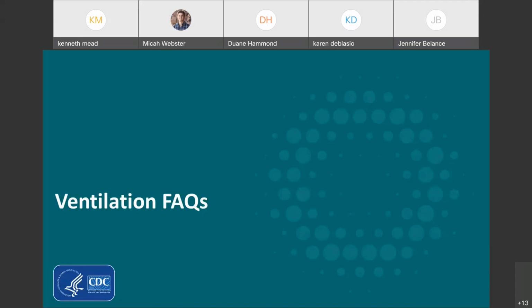There is a handheld version of that theatrical fog generator that you can also get, so you can test different areas. If you're worried about a gathering place in the corner, for instance, whether it is a dead air spot, you can release fog there. We call it tracer smoke, but it's really a water-based fog. You release it there and see what happens to the air. Does it move quickly, or does it sit and hang? Other than that, you're really required to do some measurements.